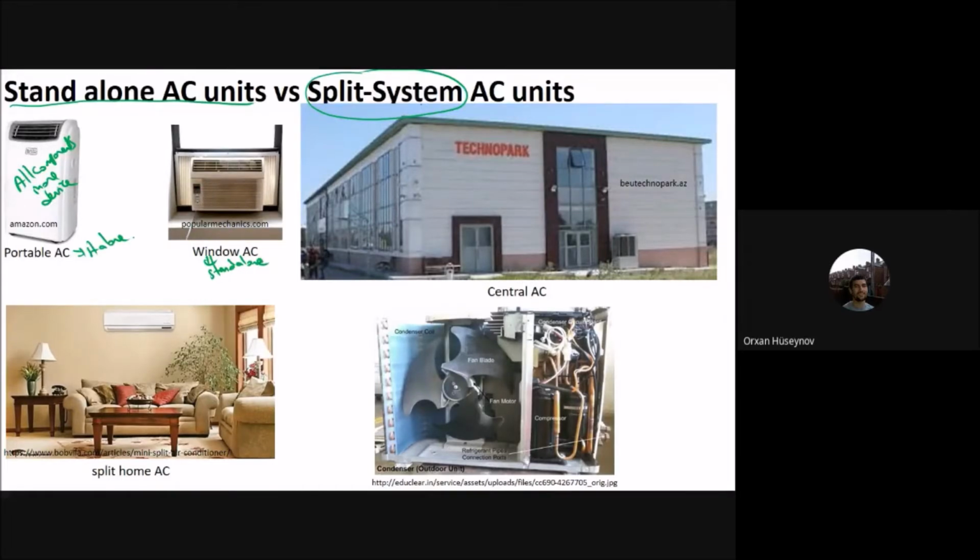And it can also be split type refrigeration. In split type refrigeration, you will have two components. Here you may have the evaporator and the thermal expansion valve, and on the outside unit you will have the condenser and the compressor. Two components in the outdoor unit. This one is the outdoor unit and this one is the indoor unit. In the indoor unit, you will have the evaporator and the thermal expansion valve, and in the outdoor unit, the compressor and the condenser. So this is a split system.